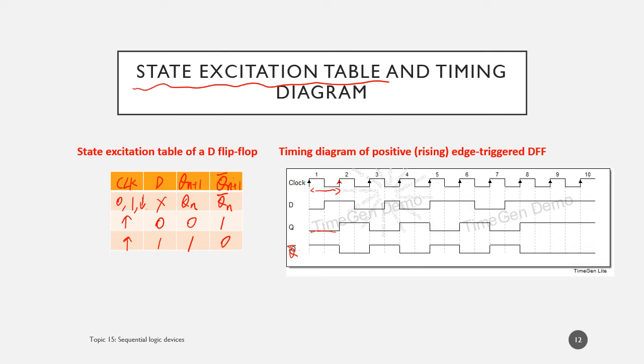At this rising edge, we know Q needs to follow D. We need to check the value of D, but we need to check before this edge. Don't check after. Check the point right before this time point. Remember, the x-axis is T. So D is 1, and that's why Q will change to 1 here.